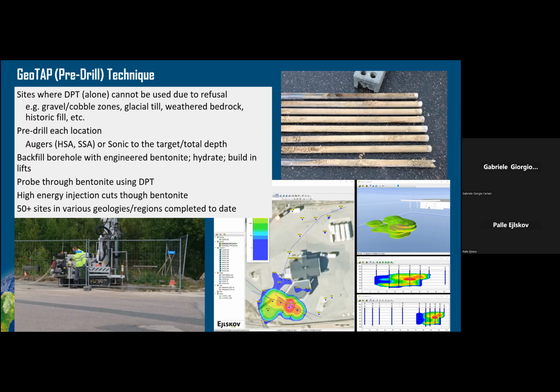So when it came to the remedial design, that was a good thing because we learned that we had to do something different for the injections. We had to reach about 18 meters to protect the groundwater, which was ultimately the goal of the remediation. The soil contamination was not deemed a risk for vapor intrusion or anything like that, but the problem was protecting against the contamination spreading in the groundwater aquifer.